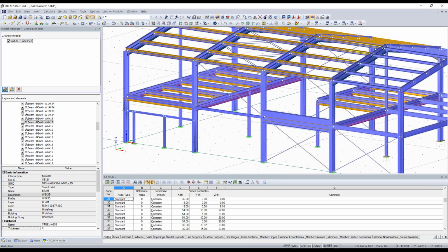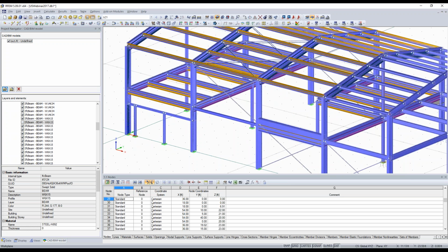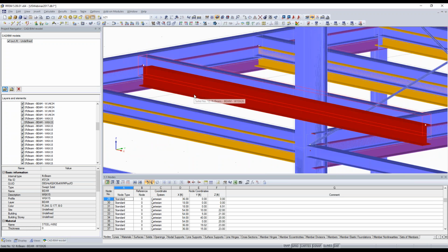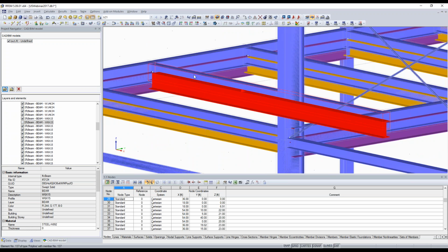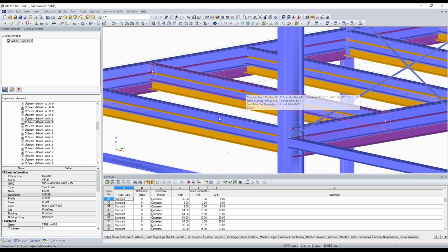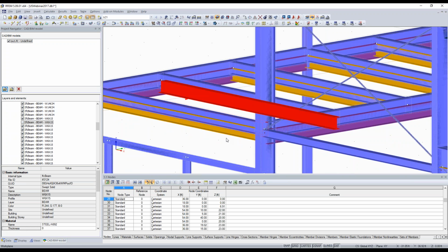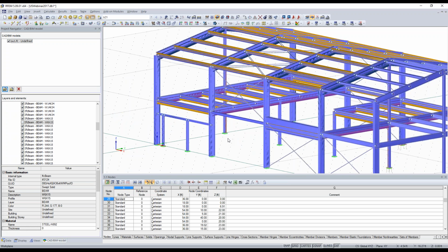but you can import also an IFC file and work with this. And also, because you see both models, you see what is the actually RFEM model and what's the difference in the original model. Yeah? So you can see originally this beam was a little bit lower than it is in the RFEM model because we said the line is on top. Yeah? The insertion line is on top of the top flange. Okay. If I don't want to see the BIM model, I exclude it.